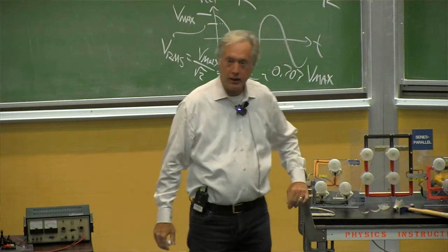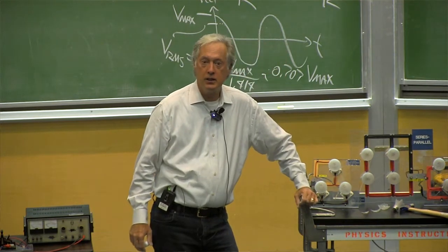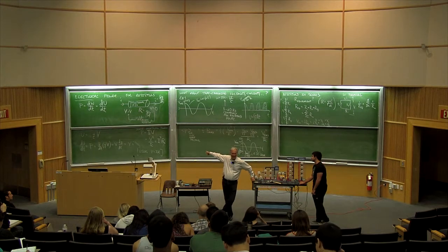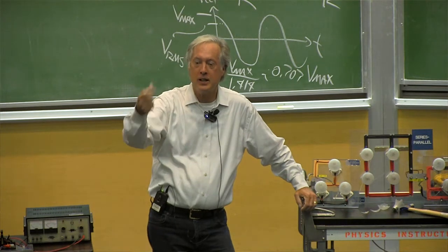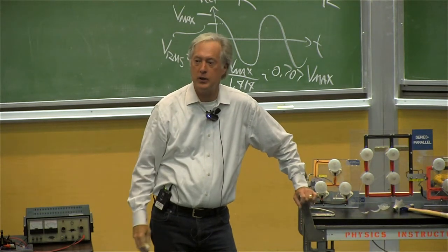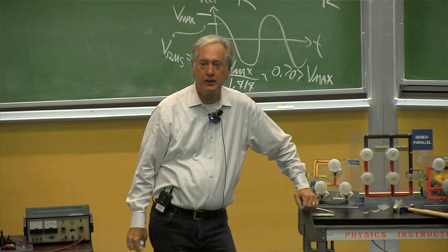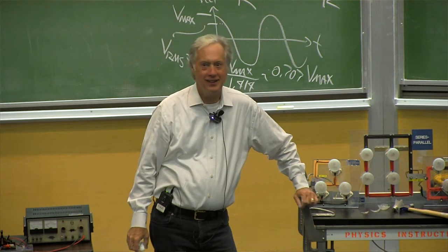Yeah. Okay, and so we know the voltage. Doesn't that tell us the resistance from over here, right? If we know the resistance, we know the length, we know the area, you can tell me the resistivity of the tungsten when it's hot. Got it?